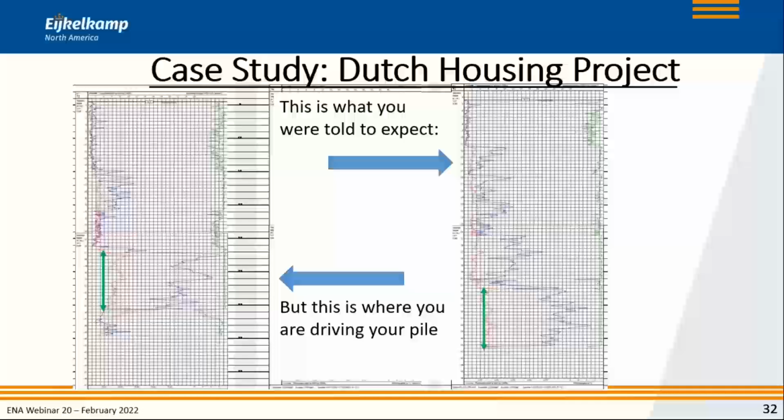In this case, we already know that it's because of site variability. But if you have missed that, or you haven't done an extensive soil investigation, you don't know what the reason is for the obstruction. And by doing a CPT sounding right then and there, you can find out what is happening, why you have this obstruction, why you have these problems driving the pile.